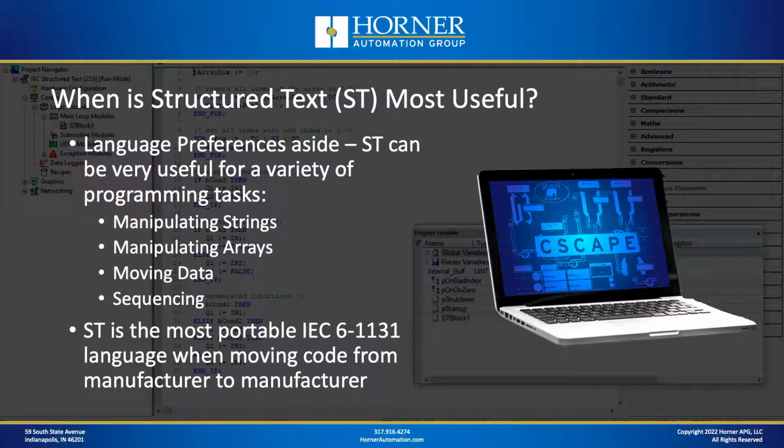Now, what are the situations in which structured text is most useful, besides the fact that multiple language support is one of the real benefits of IEC? When might I choose to use structured text for a particular task? Well, structured text is great for manipulating string data, manipulating array data, for moving data around in general, even for sequencing. And also keep in mind that structured text is the most portable IEC 61131 language.